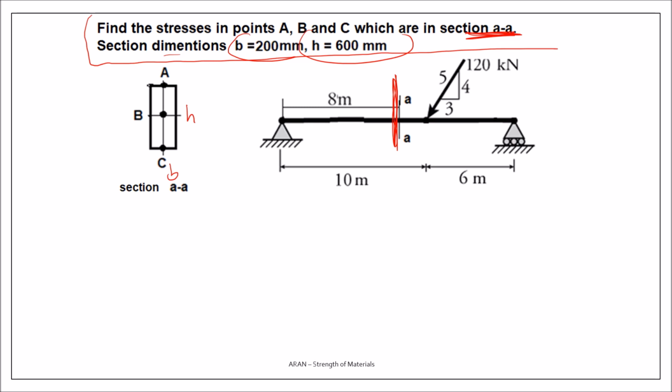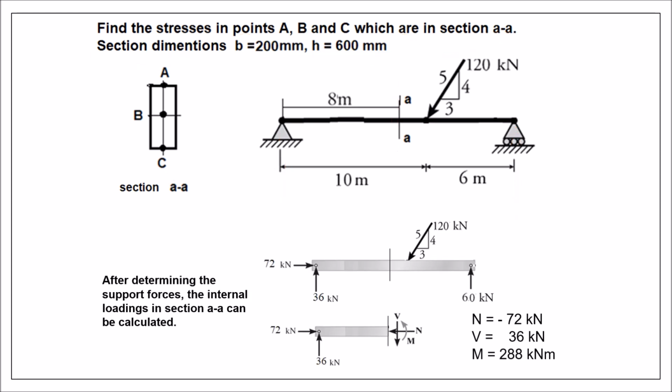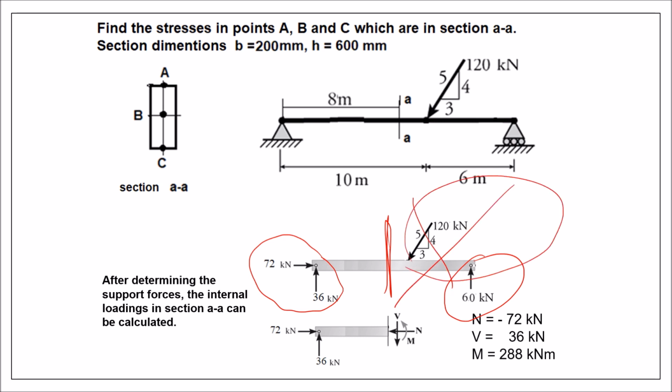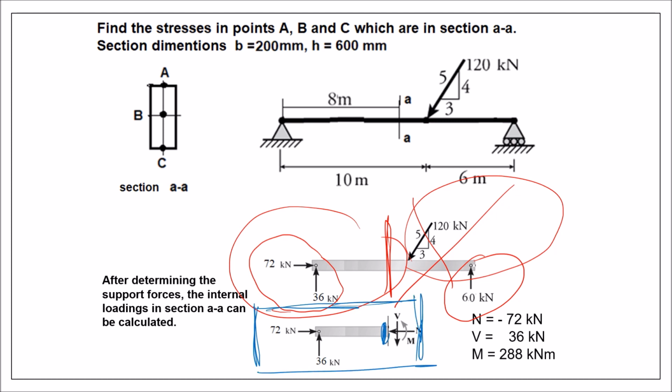So the first thing I do is to find the support forces, and you can do it by equilibrium. These are your support forces. You cut here. Well, the right side is more complicated. Let's take the left side, and this is the left side you have to consider. You take this free body diagram and you try to find the forces and moments in this section.